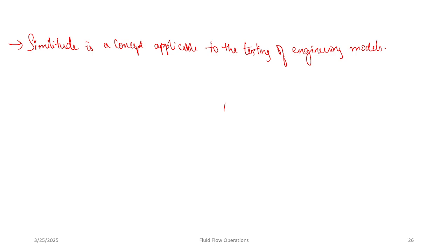In order to have a complete idea about flow devices, it is essential that the model should represent its prototype completely and fully in all aspects. The similarity between the prototype and its scale model is known as hydraulic similitude. Overall, the conditions that a model of a phenomenon reproduces all aspects of the behavior of a prototype represented by it are known as conditions of similitude.